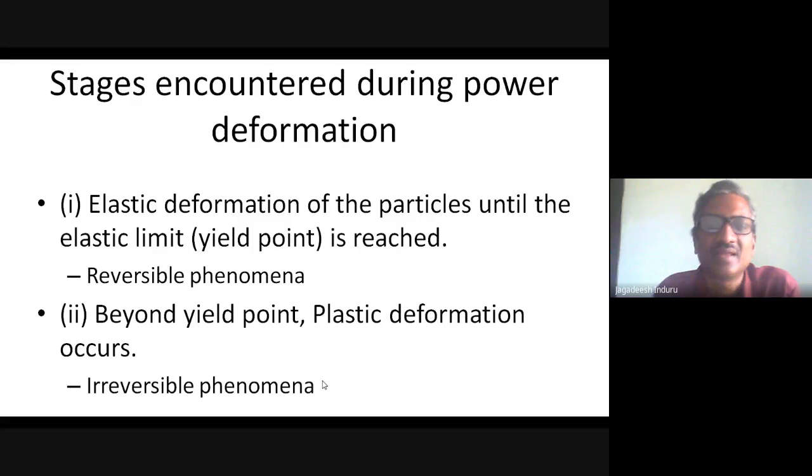But in this particular issue, the yield point or critical force that we are applying is going to be our target point, so that we can have successful tablet manufacture or size reduction or not. Because beyond that point only will we have an irreversible phenomenon.